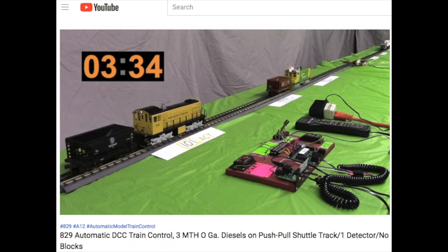Now the first engine stopped. You can see the second engine's in motion. And it'll just keep going until that engine crosses a detector, which you can see it'll go to red in a minute. There it did. Now the mini panel, that is to say the controller, it's executing an 18-second time delay to position that green engine down in the location where we want to park it.